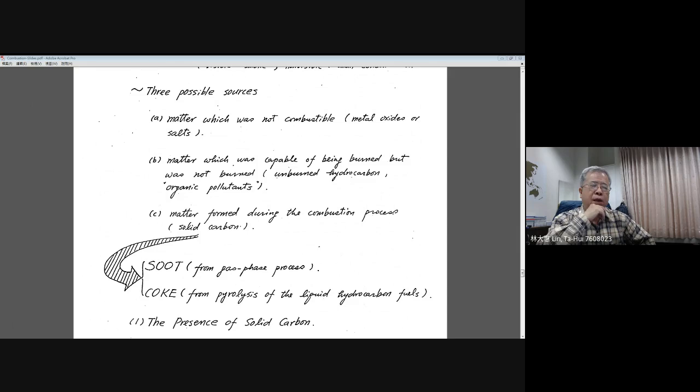And the completion of the combustion process depends on, as I just said, the gasification process and also the mixing process, because when the hydrocarbon comes out, it needs to mix with oxygen from the air. If the mixing is not properly controlled, then you will have a small pocket, and this pocket may contain too much fuel, and you cannot finish it.